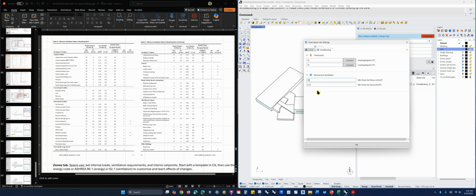The point is, we're setting this because we talked about this in previous weeks, right? If we're going to be bringing in fresh air, that means we're going to be exhausting interior air because we have to be balanced. We can't just keep putting more air into the building or taking it out, because we need the same amount of air in the building at all times. And that's going to cause us to lose energy, right? So we're going to have our nice 72 degree heated air inside, and then it's 25 degrees outside.